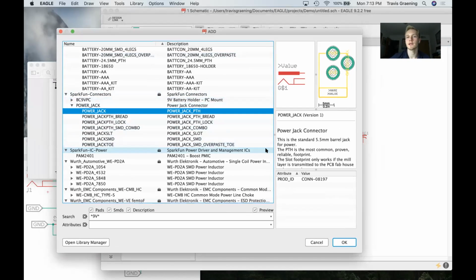And so for those of you in Micromouse and Ops, one of the things you're actually going to be doing, if this year is like all the others, is selecting all your own parts. So once you do that, it becomes a lot more important which footprints you select and which exact parts you use. There are certain websites where you can look up exact parts and then download a library or a specific outline for it that'll give you both of these, so you can make sure you're using exactly what you need.